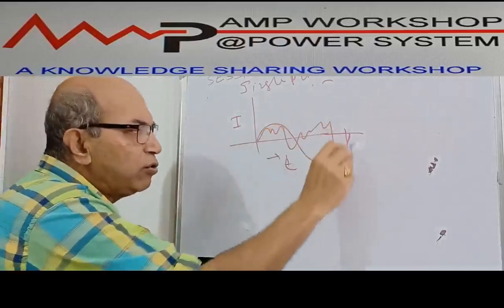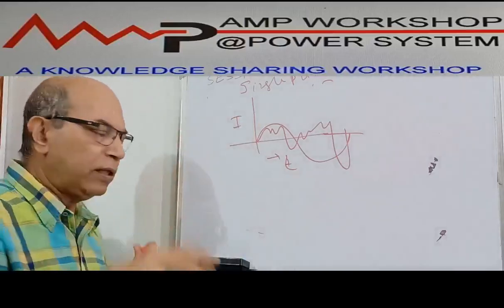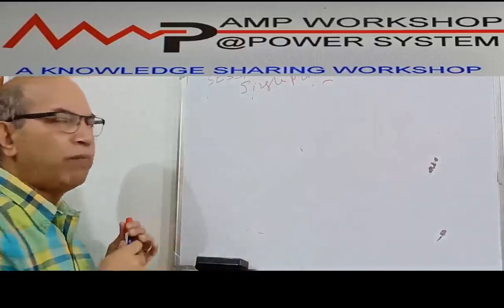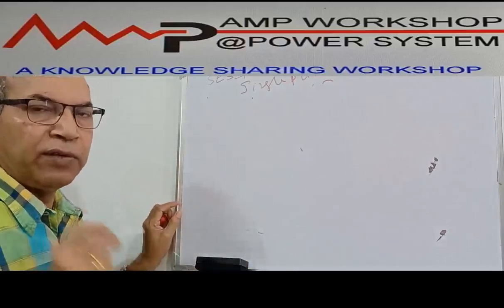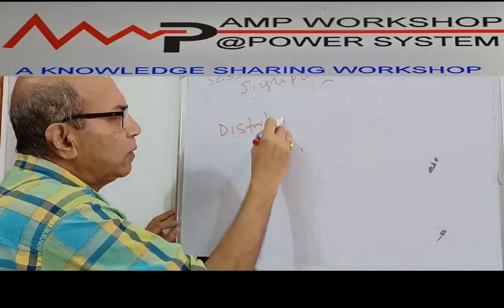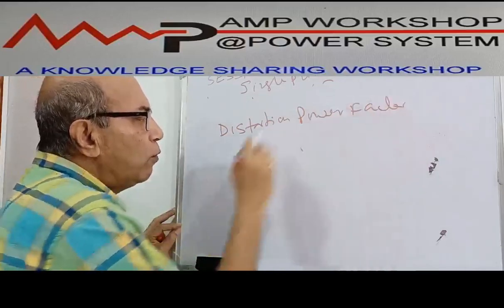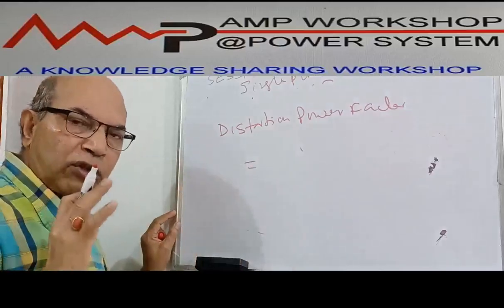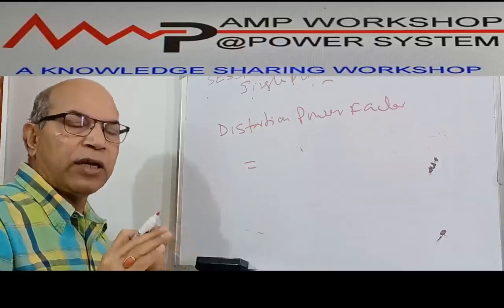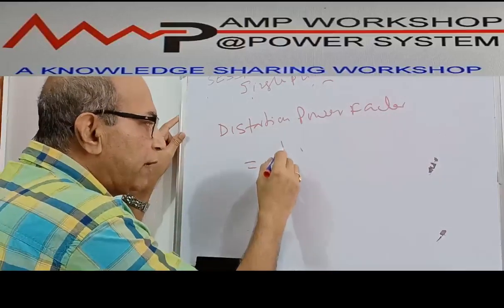So this has a huge different impact on this circuit. To discuss this part, we have to capture all the harmonics which are present in the supply. Now how will we calculate it? To calculate this, we first define the distortion power factor. How do we define it? Distortion power factor is defined with respect to the fundamental frequency as well as all the harmonics.